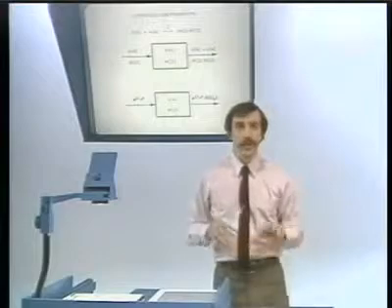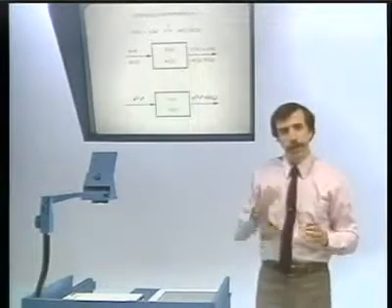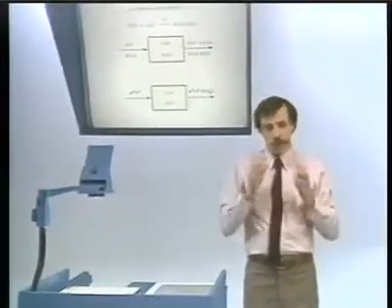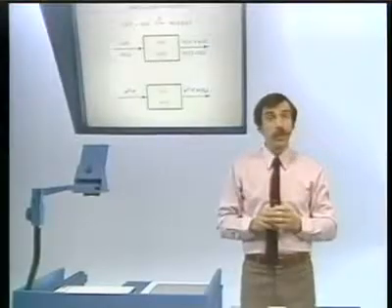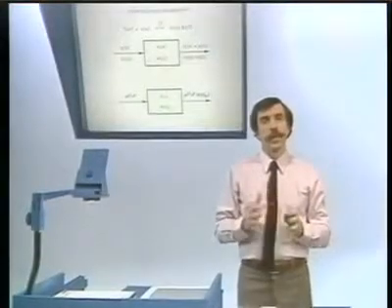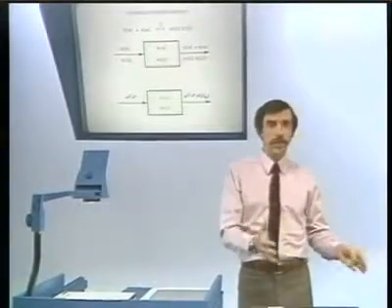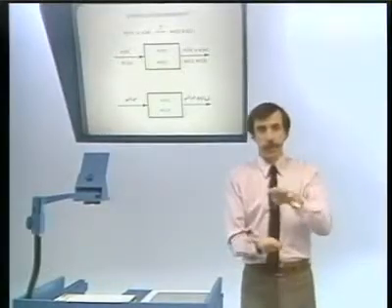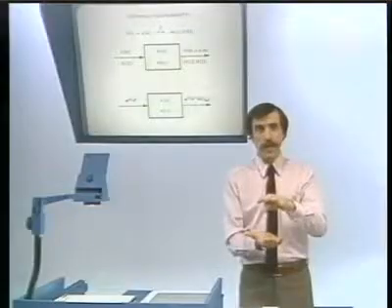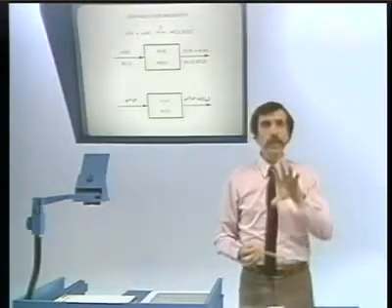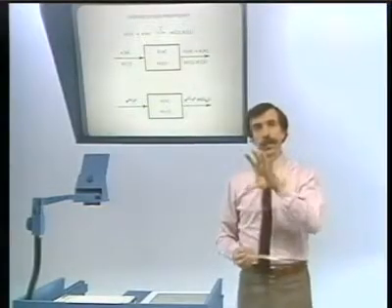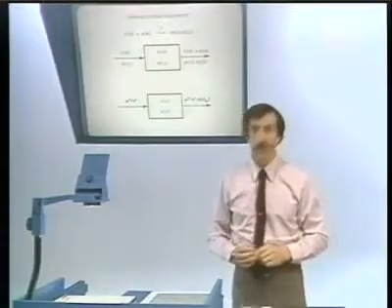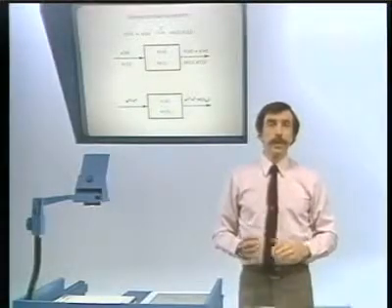So it's important in thinking about the convolution property to think about it in terms of nothing more than the fact that we've decomposed the input and we're now modifying separately, through multiplication, through scaling, the amplitudes of each of the complex exponential components.